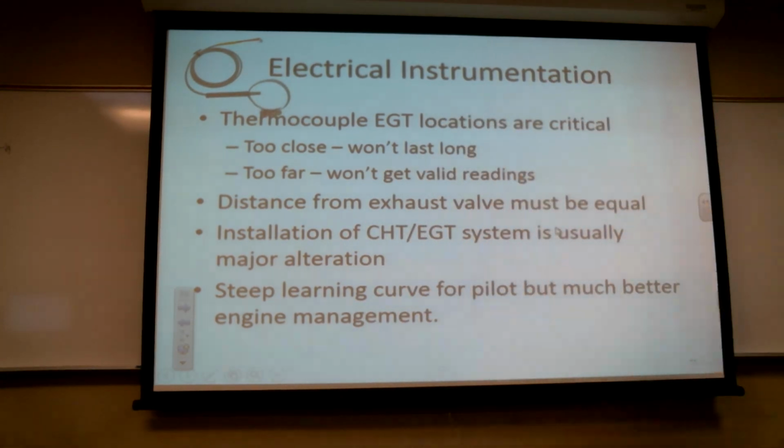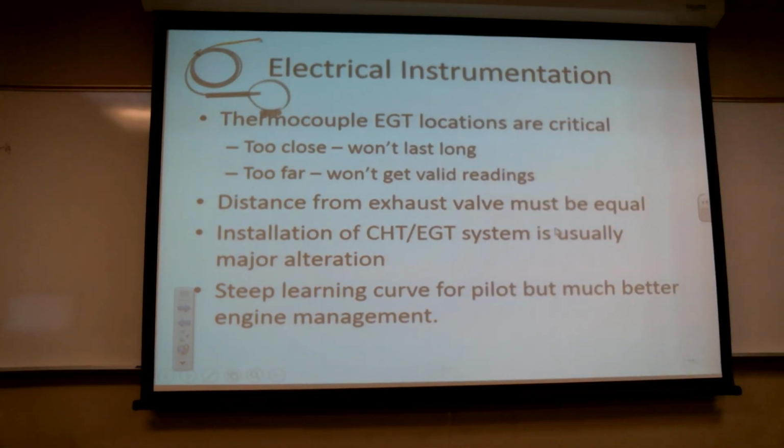So the question is, where do you put the hole? 12 o'clock. Self-adjusting one? I don't know. The hole is self-adjusting? Come on. The thermocouple is going to be giving you literal readings of some value. The truth is, we don't really care what they are. What we care about are the relative values.